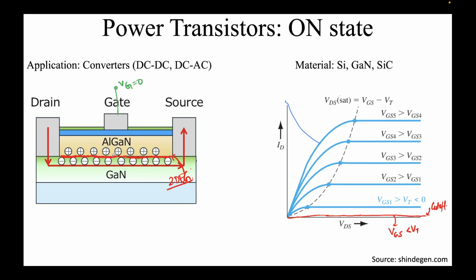Here the threshold voltage is where this sheet of electrons disappears, and you can see that the sheet of electrons will disappear only when I apply negative voltage. It's naturally present at Vg equal to 0. So if you apply, let's say, Vg equal to -1, some electrons will be repelled away below the gate. -2, more will be repelled. There will come a time when you will repel away all the electrons, right?